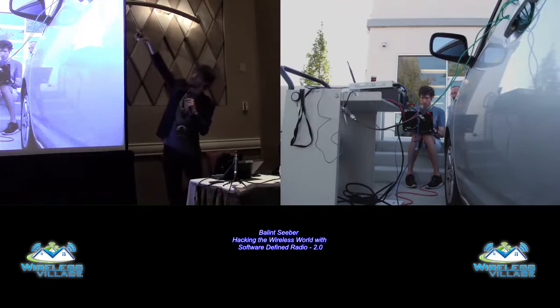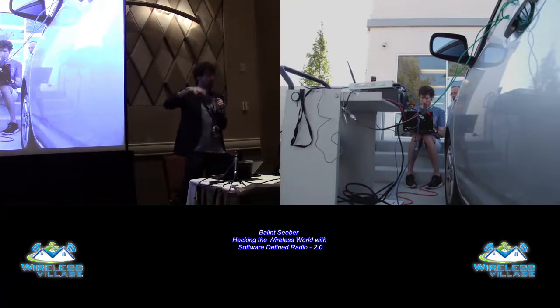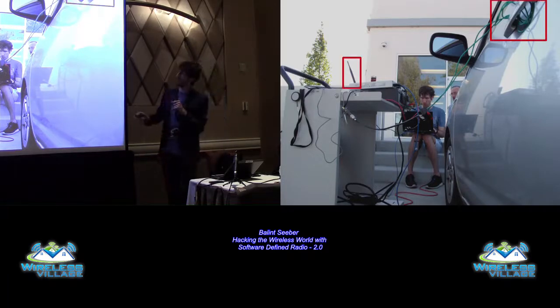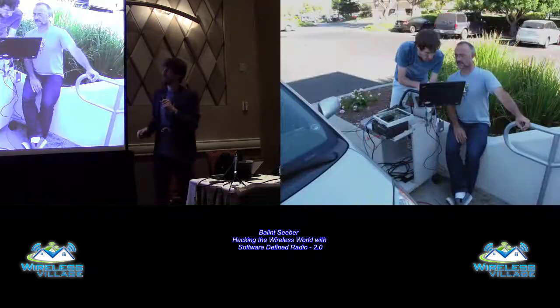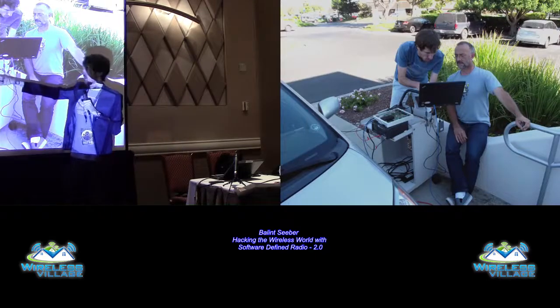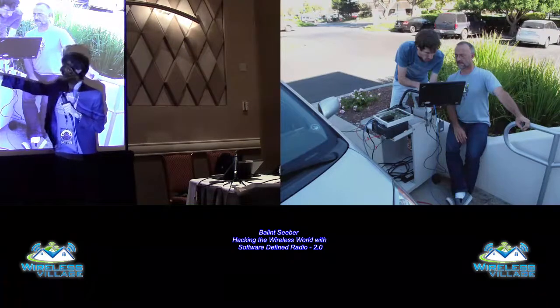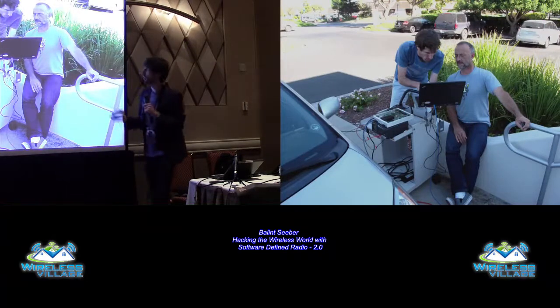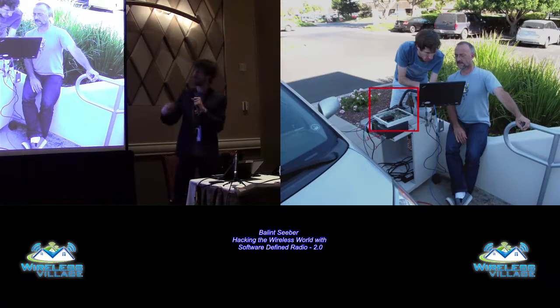We've got that wire there stuck in the handle, which is where the low frequency broadcast comes from the car that wakes up the little UHF remote control. And the UHF portion we're receiving on that little whip antenna there. Here we're actually using the X310 because we're doing LF recording with one side of the one channel, and then VHF, UHF on the other side. And then my colleague here is just pressing the button on the remote sometimes, so we get some additional activity.